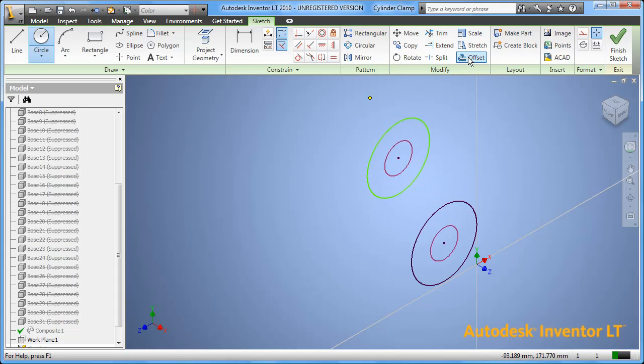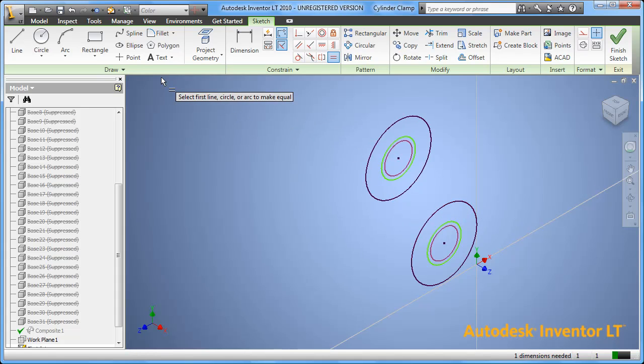In Inventor LT, the creation of a 2D profile is created initially based upon a sketch, which represents a loose approximation of the overall shape. That sketch is then refined based upon constraints, both geometrical and dimensional. By adding constraints, that sketch is converted to a fully refined shape.